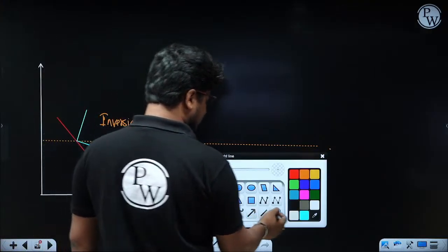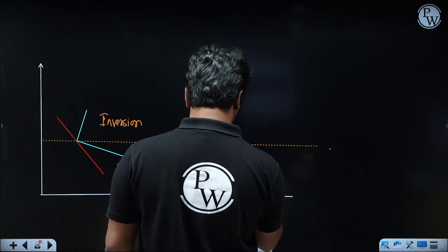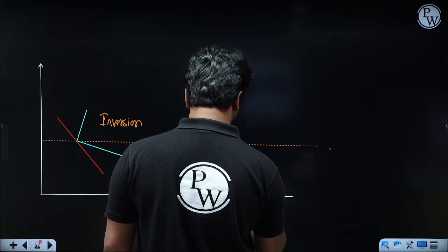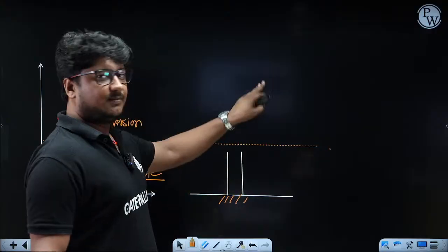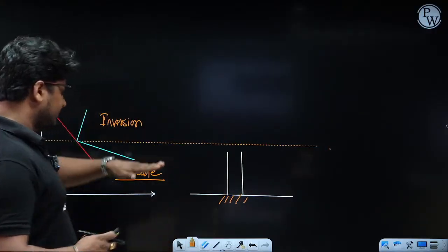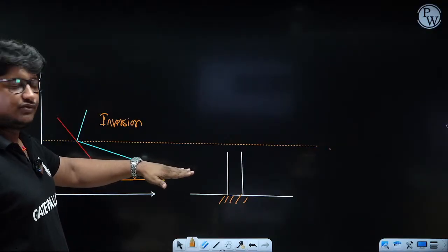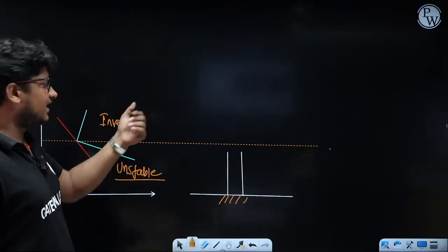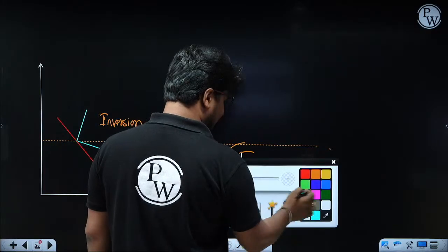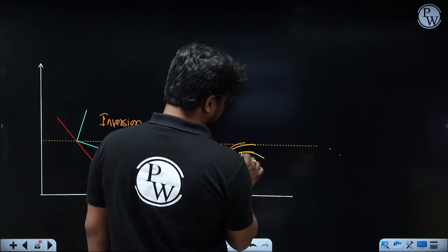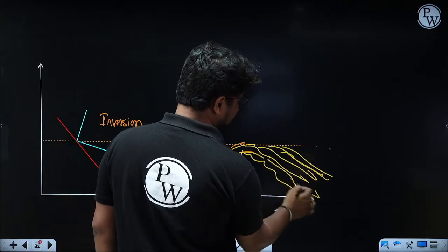Now in this condition, if any pollutant comes out, do you really think that pollutant will go vertically upward? The top layer is the inversion layer, and the bottom layer is a super adiabatic, or super unstable, layer, and above that unstable layer you have the inversion layer. So any pollutant which comes out from this chimney will only go towards the ground.